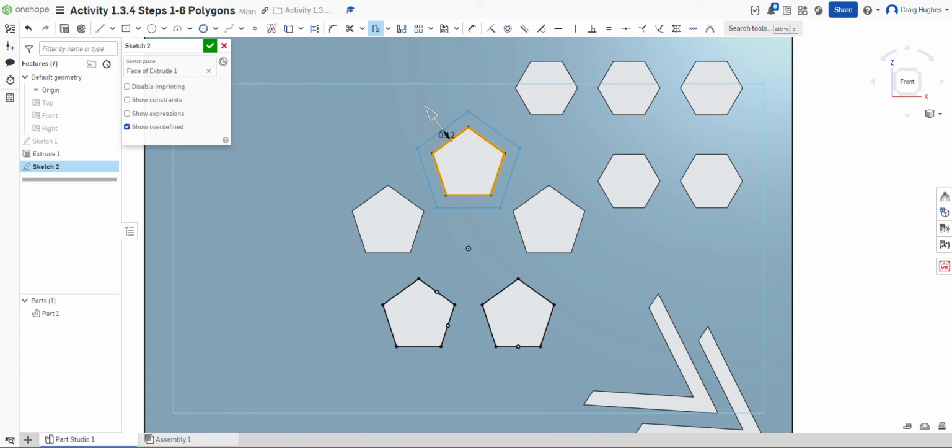And then they'd like us to apply a 0.2 inch fillet to the corners. So again, I can always type in there 0.1, and then they would like us to apply a fillet. Within the sketch environment, you're going to see the sketch fillets right here. We're going to apply that fillet of 0.2. So the radius will be set to 0.2. And I'm just going to go around and keep selecting these lines.